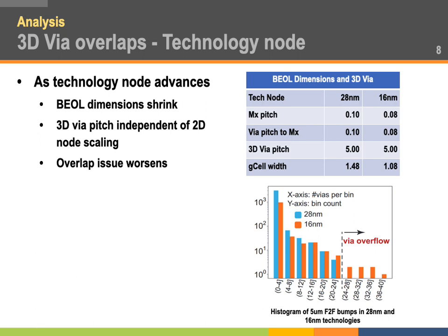that they're strictly legal, because there can be a large density of vias where 4 or 5 vias can be pretty close to each other, overlapping, and they can be the only vias in that 25 by 25 bin. Then there won't be any overflow, but there are still overlaps. But it means that these overlaps can be removed within the same bin itself, and they won't be quite severe as we don't need to move outside the bin.